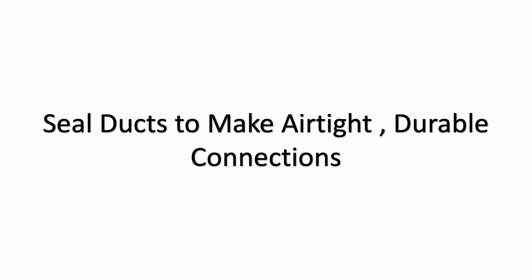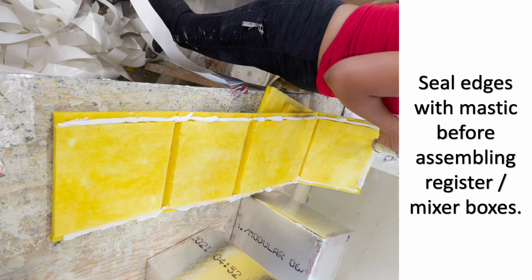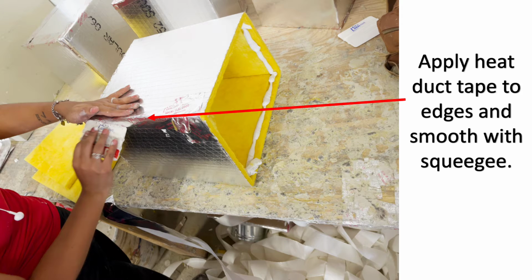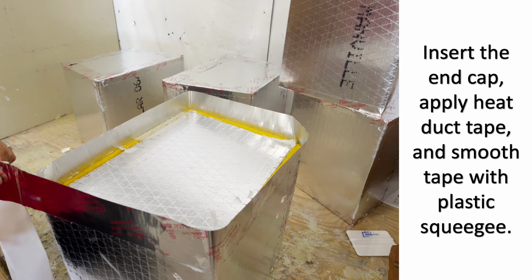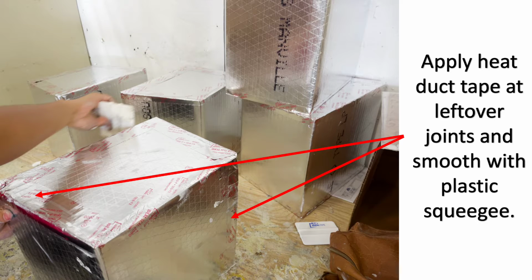Seal ducts to make airtight, durable connections. Seal edges with mastic before assembling register mixture boxes. Apply heat duct tape to edges and smooth with the squeegee. In case there is a gap at the end cap, fill with mastic and apply heat duct tape. Insert the end cap, apply heat duct tape, and smooth tape with a plastic squeegee. Apply heat duct tape at leftover joints and smooth with a plastic squeegee.